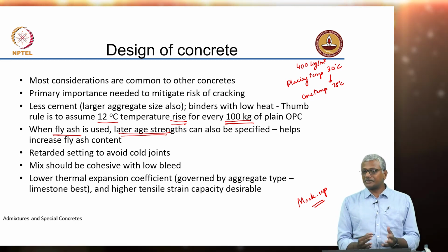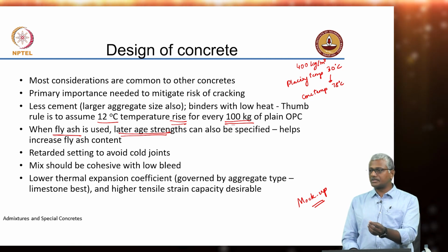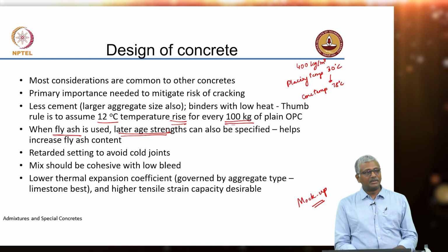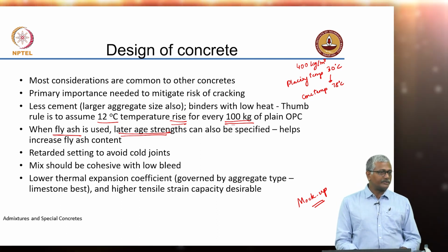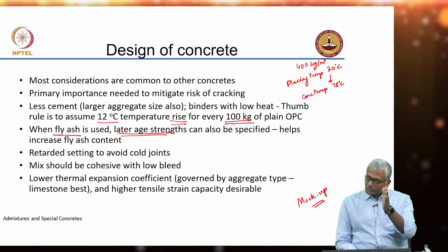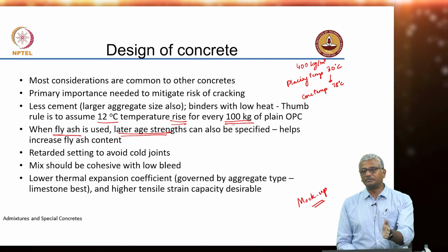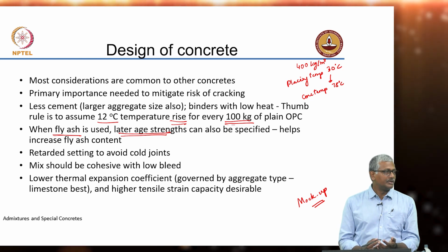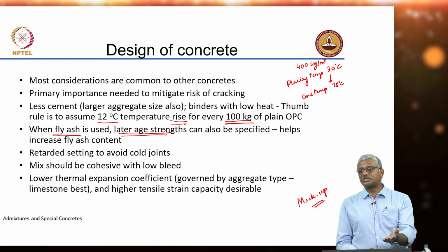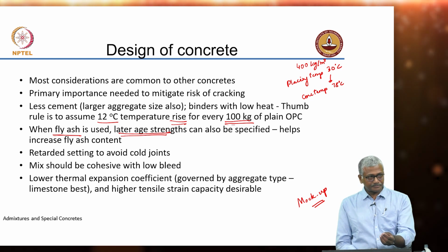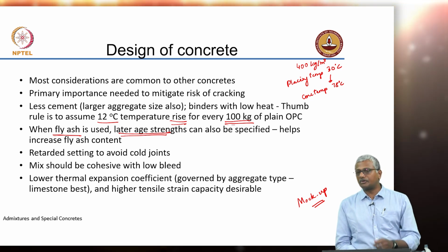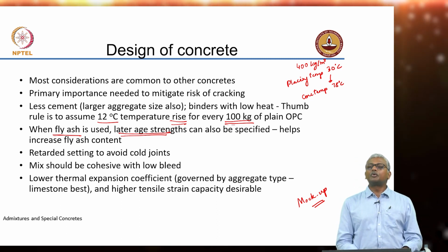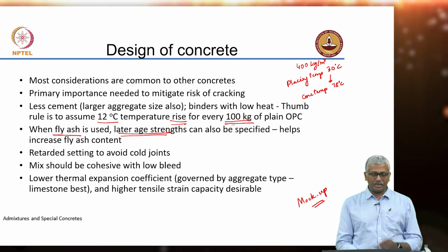So, all of these show that with a careful consideration of the quality of concrete that is required for a particular project, you can actually meet the demands. So, as I said, choose as low a strength as possible for the raft or for the footing or for any mass concrete structure. Use as much replacement of cement as possible, and because of the delay that will give in your strength development, try to go for a later age strength for approval of the mix and not 28 day strength.